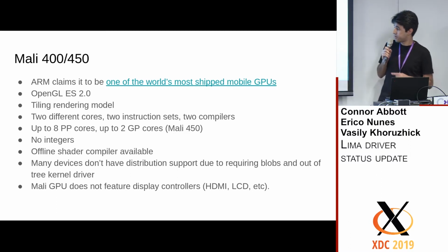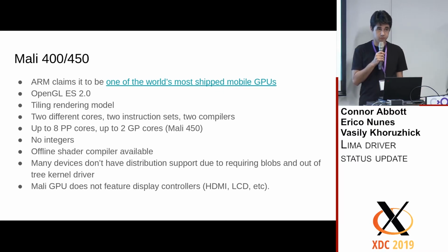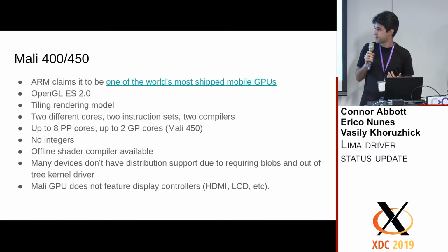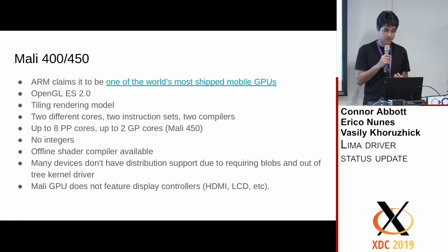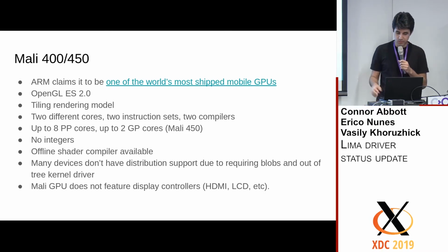And finally, I would just like to mention this for the record. The Mali 400 and Mali 450 do not have display controllers, so the GPU does not really have anything to do with the HDMI display or the LCD. It's a completely different piece of hardware and a completely different driver. So if there's a problem with that, it's most likely not related to the actual GPU.